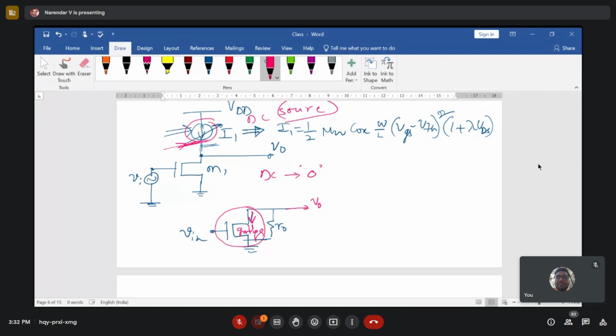So you take this MOS transistor and its small signal model and try to analyze it. Or else we just consider the gate and the gate to source voltage VGS. This is R0, and this is gm times VGS. Now we are representing it in the transistor symbol itself. In the transistor symbol itself, we indicate this is R01 and this is V0, and the source is connected to the ground terminal. This is what is depicted.